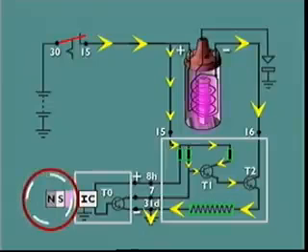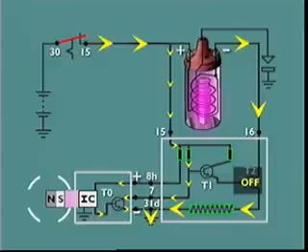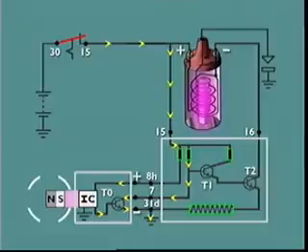With distributor rotation, the blade exits from the air gap and a window enters. The magnetic field at the whole assembly now permeates the whole generator and its integrated circuit, and the signal voltage turns on the base emitter of T0. The circuit, now established through the collector emitter of T0, diverts current away from the base circuit of T1, and T1 switches off. Since T2 cannot function without the action of T1, T2 also switches off.